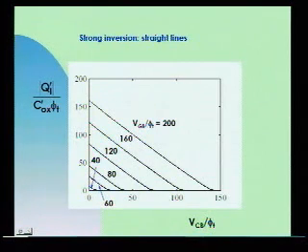In strong inversion, I will have the inversion charge density as, I want to say linear, because linear means passing by the zero. How do you say that? A first order polynomial, I could say like that. It's a first order polynomial, either of VCB or of VGB.